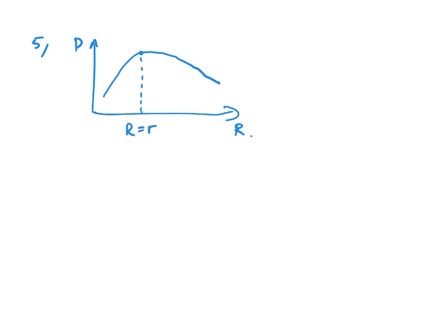And the final outcome is the idea of load matching. It's basically the concept that if you change the resistance in the circuit and measure the power delivered to the load resistance, what you find is it will peak and then drop off. And the value of resistance which produces that maximum power is when the load resistance equals the internal resistance. And this is called load matching.